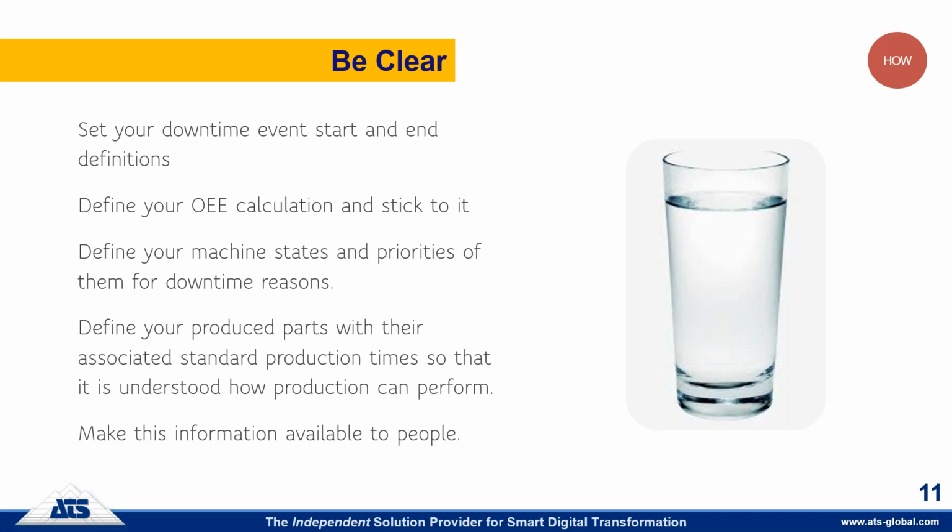If you had multiple events triggered that could cause a downtime, you need to be sure you're capturing the one that has the highest priority and would actually stop the machine. If you're prioritizing your production scheduling, then perhaps you would prioritize starvation over a machine fault. It depends on what aspect you're trying to improve as to how these priorities are set.